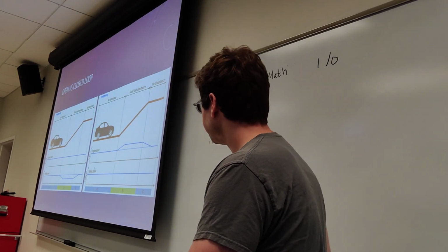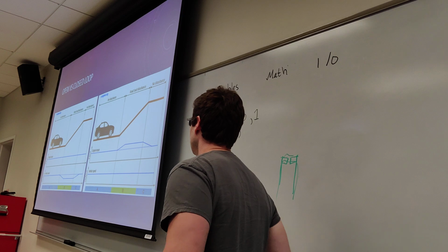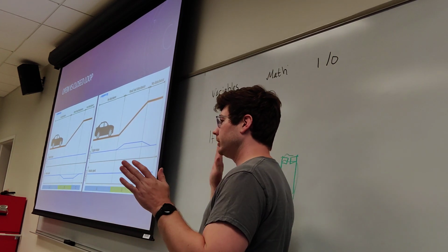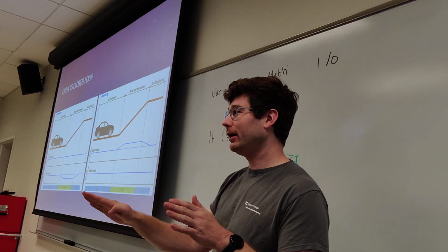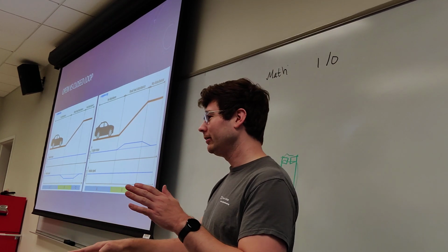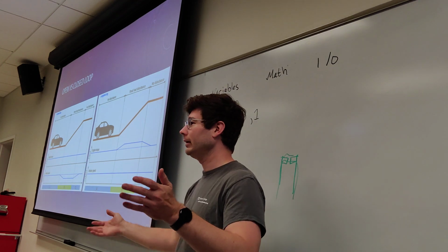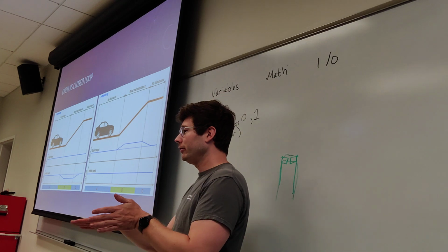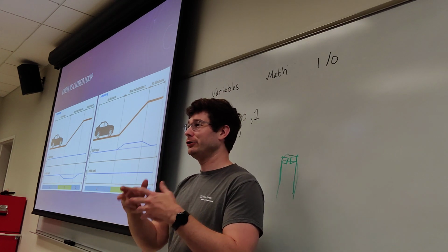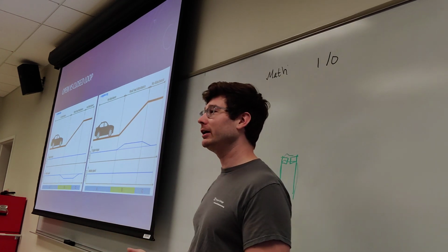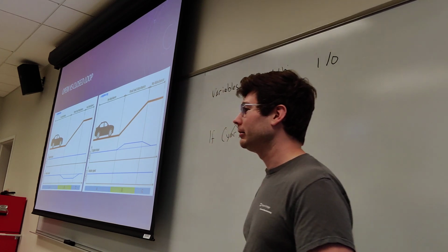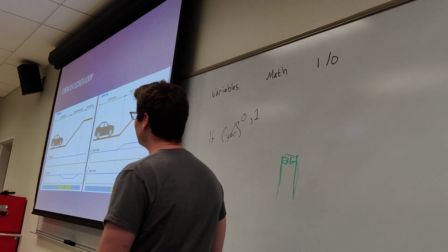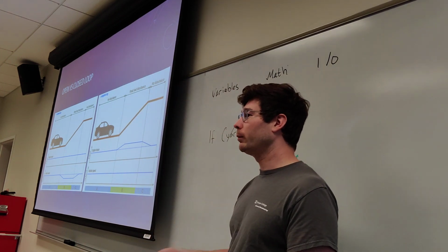Another way to think about this is, if you have a car and you know from your past experience that if you push the pedal down this far on a section of highway, you'll go approximately the speed limit, that is open loop control. If you are in a residential neighborhood, you know that you can be this far on the gas and you'll be going such and such speed. For 90% of use cases, that would probably work. This happens a lot in industry where 99% of use cases can be solved with an open loop solution. It probably will be.